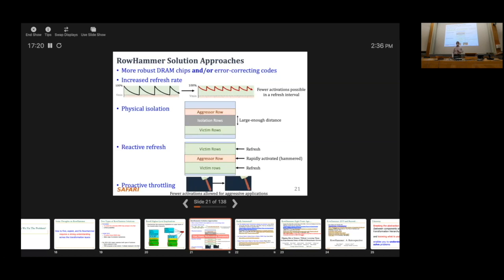Okay, that's great. Maybe you should talk to a guy over there who looks at the relationship of voltage and RowHammer. Potentially, that could be a solution, but it's not a problem with just voltages. DRAM actually operates at relatively low voltages compared to, for example, flash memory. Maybe if you go to extremely low voltages you can eliminate this, but we don't know how to do that yet. Any memory technology that we develop, whether operating at high or low voltage in today's range, has this sort of problem. It's called read disturb in general, and flash memory also has this problem, except it's not as bad in flash memory because you already have intelligent controllers in your SSDs that can solve this.